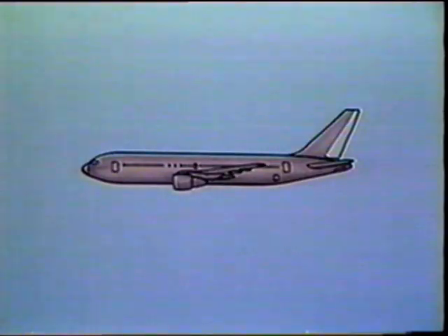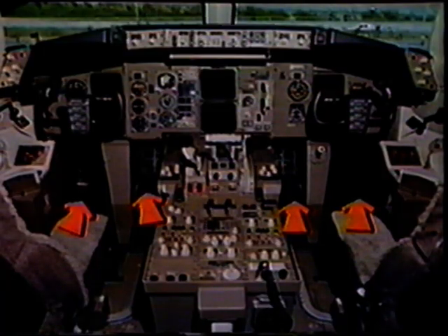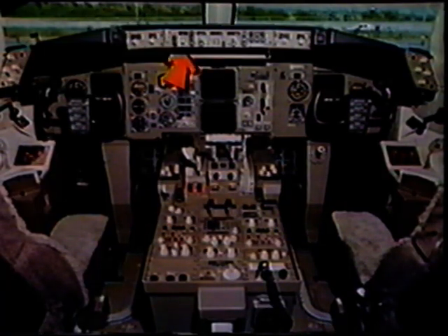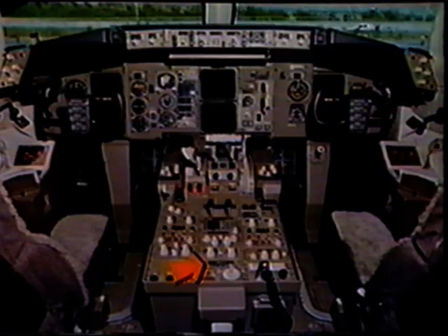The last of the control surfaces on the tail section of the airplane is the rudder. The rudder is located on the trailing edge of the vertical stabilizer and provides continuous directional control of the airplane about the yaw axis. The rudder is controlled by pilot input commands on the rudder pedals. It is also controlled by the autopilot control system during landing. The rudder trim knob and trim indicator are located on the aft pilot's control stand.